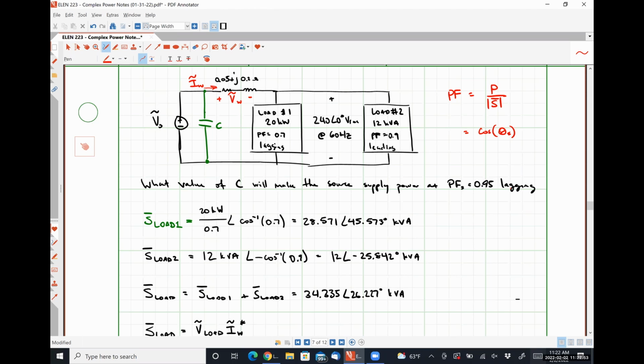Okay, so that's a great question. To hit a power factor of unity would require a larger capacitor value, which may require a physically larger capacitor. So it's all about the cost. Most of the decisions that are going to be made in industry regarding power factor correction and all that kind of stuff are all related to cost. How can you do it as efficiently but cheaply as possible?